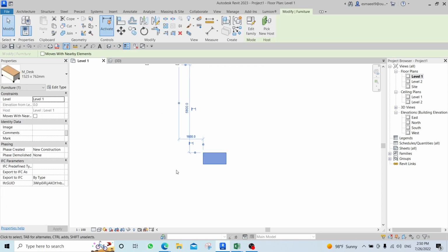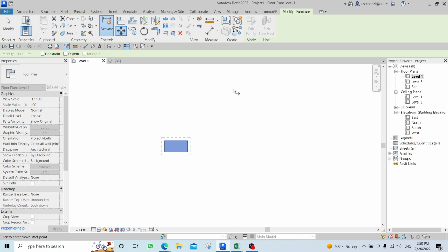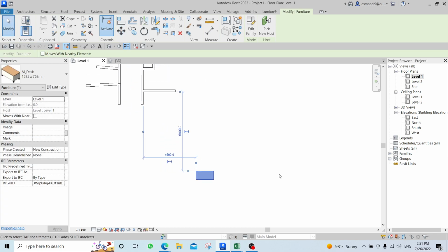This office, I want to move it to the right side 3000 millimeter. MV, click any point I want. It doesn't matter, I don't have to click in it. Anywhere. In here, move like this to the right, 3000. Let me see. Am I okay? 3000. Okay. I moved it.